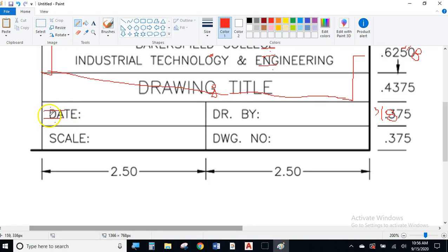And then on the side, we're going to move it over an eighth. So all of these have the same jog. They're all jogged over an eighth, and they're all jogged down an eighth, and they're all an eighth tall, which centers up things nicely. Okay, these can be regular left justify, because we want the bottom left corner of the text to snap into that point right there and right there.